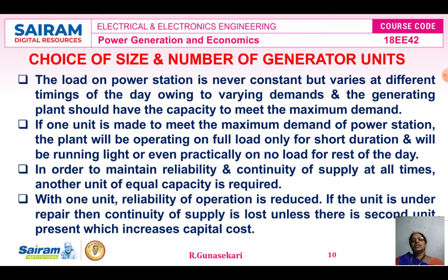Generally the size is directly proportional to rating. If the rating of the generator increases, definitely the size of the generator also increases, the cost increases, the installation cost increases, the total capital cost increases, and the maintenance cost also increases. So therefore the choice of size is a very, very important factor.